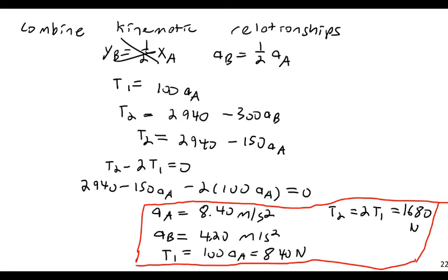So again, if I look through my basic series of steps, first I want to set up any basic kinematic relationships that will exist between any conjoined or dependent parts. If there's a pulley and a string, or two objects glued together, anything like that, I know I'll have some sort of dependent motion. So I immediately write those down and get some points on the board, basically.